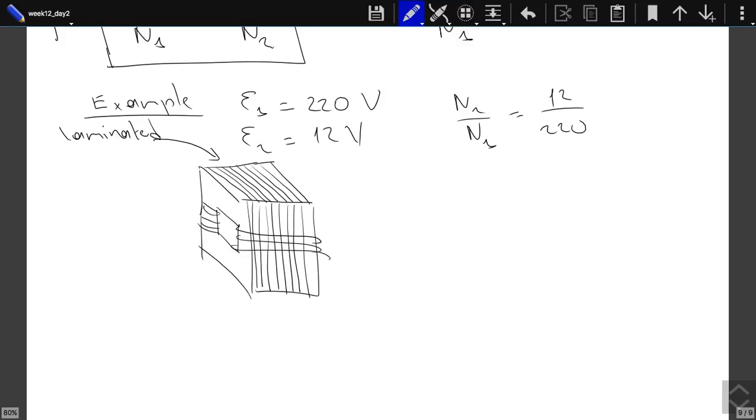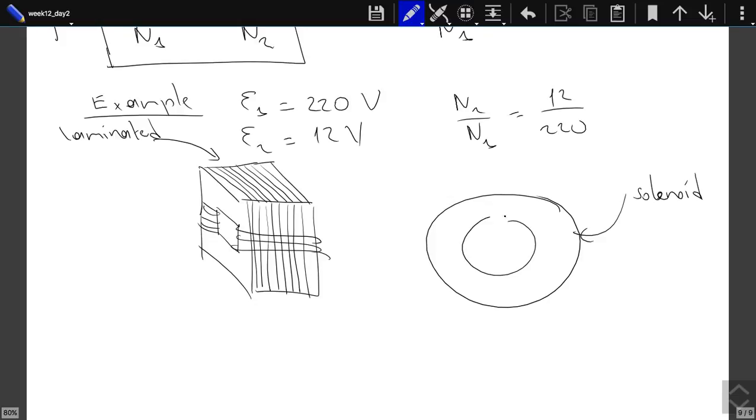The eddy currents. You see, we had seen that if you have such a solenoid, there will be electric fields induced inside, circular electric fields. So this is I. But those circular electric fields, if you have a conductor like iron, will create currents. Iron does not have such a small resistivity, so iron will resist the current, it will dissipate power, and it will become hot. So that is not what you want. The currents will be basically just going in circles, the eddy currents.